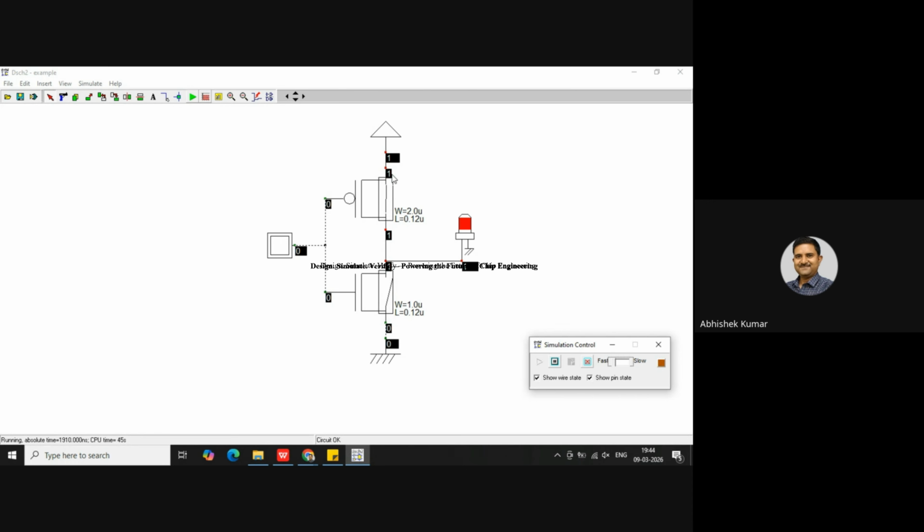Since this is the closed path, the power supply, which is binary 1, is connected up to here, so my output, connected to this drain terminal, gets binary 1. But this NMOS is off, an open path, so it is not connected with ground. In this condition my output is pulled up, generating a high output. So in this case the PMOS provides a path through which the output will be pulled up to VDD.